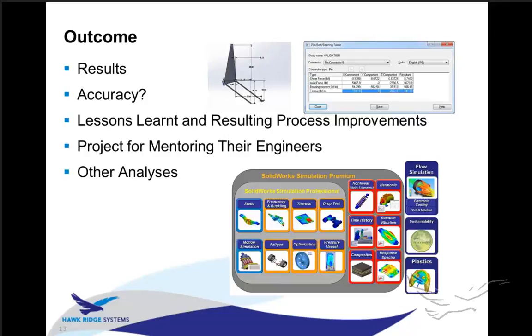There are other tools inside the SOLIDWORKS simulation family that can help these guys in understanding their process. A couple of them that come to mind are the fatigue analysis, being able to run this over 10,000, 100,000 cycles to see what kind of stresses actually develop and how long this product will last. Optimization is a really awesome tool. It allows us to optimize different components of the design. We can say, hey, we want to put a hole in this model, and the hole can be a certain size to lighten the weight, but we want to keep it under a certain stress. SOLIDWORKS will go through and optimize the design to get the right size hole.